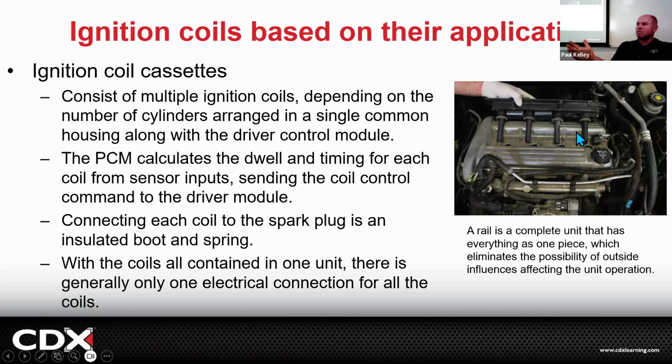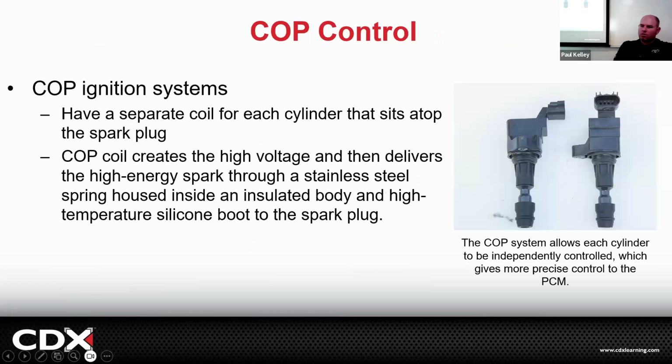And you're like, why'd they make this? Well, at the time, people were happy about it. But now that they're old, not so much. This one, the coil on plug, I got to tell you, I really do like this. When we get into coil diagnosis, you can see we can do that waveform and we can take a lot of measurements. We could do a lot of stuff. It takes time. It's a pain in my butt.